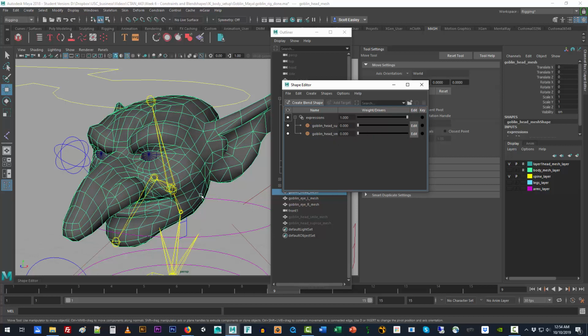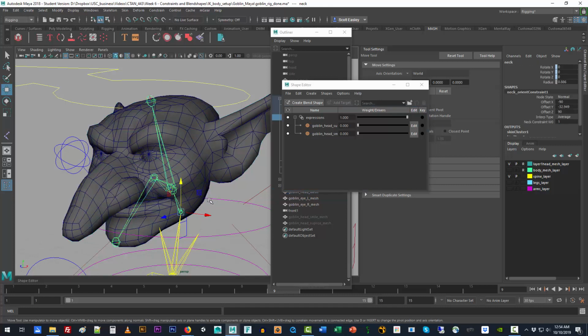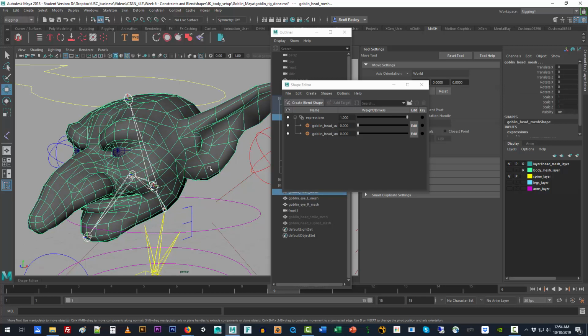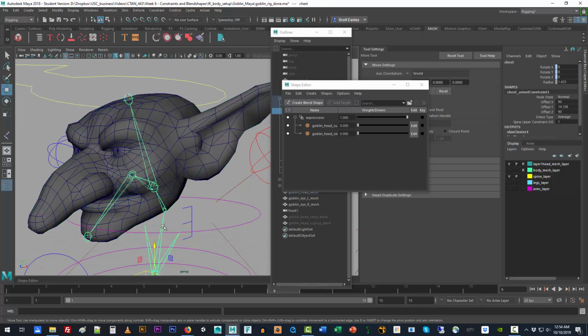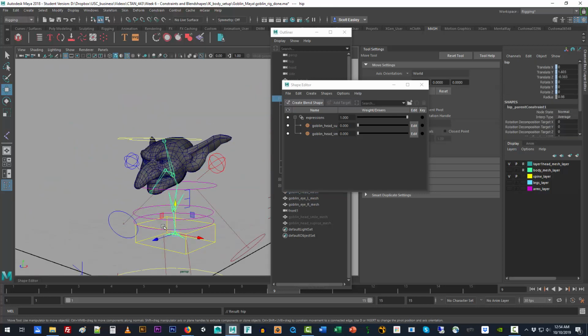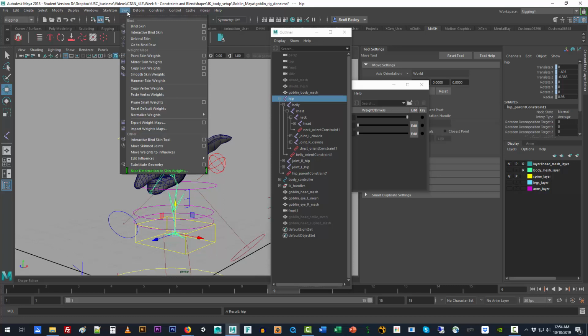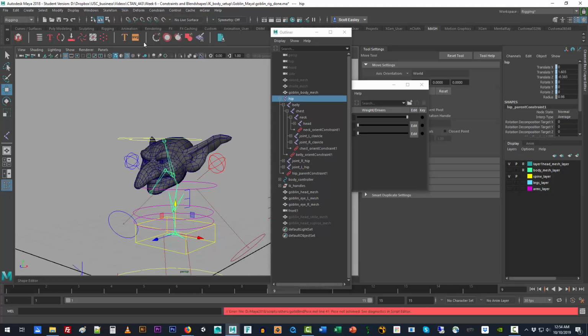So that's wonderful. So select the head bone and then shift select the head geometry. By the way, one of the things you want to do with the skeleton first, if you want to select the whole skeleton, you want to go up here in the rigging mode and make sure that before we bind, you actually have gone to the bind pose. And apparently, pose not achieved, seek diagnostics. Let's figure out what's going on there.